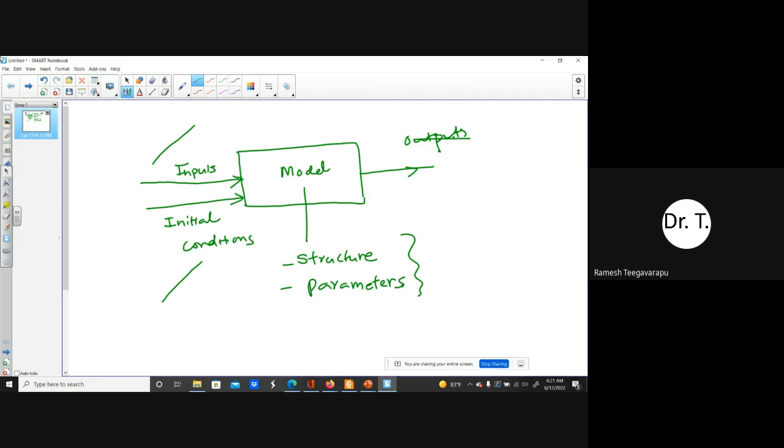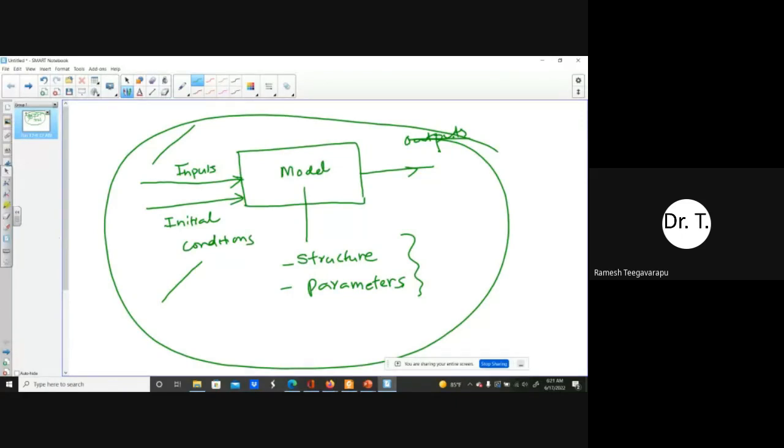In inductive models also, obviously, there is data uncertainty, that is input uncertainty. If your upstream conditions are not measured correctly, or if there is some problem with the instrument, or if you're not sure about the estimation you have done for that particular stage, you'll always end up with some kind of wrong output. You might end up with negative values of your streamflow or negative values of your stages. So there is some uncertainty even with the inputs you are providing to inductive models. So this structure where we are using the concept of understanding the system is what we call the deductive model.